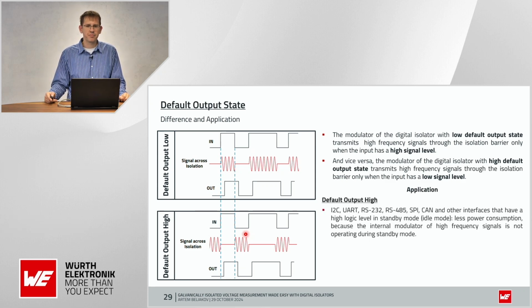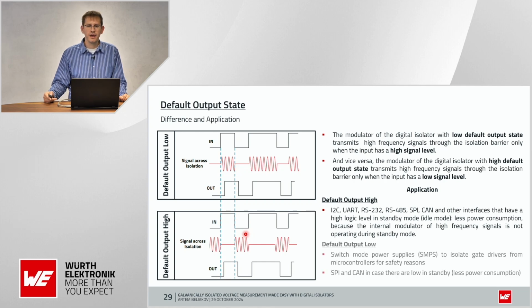Now let's speak about application. Of course, for the most popular interfaces on the market, it makes sense to use digital isolators with default output high, because those interfaces have a high logic level in standby mode, idle mode. It means less power consumption because the internal modulator of high frequency signals is not operating during standby mode.